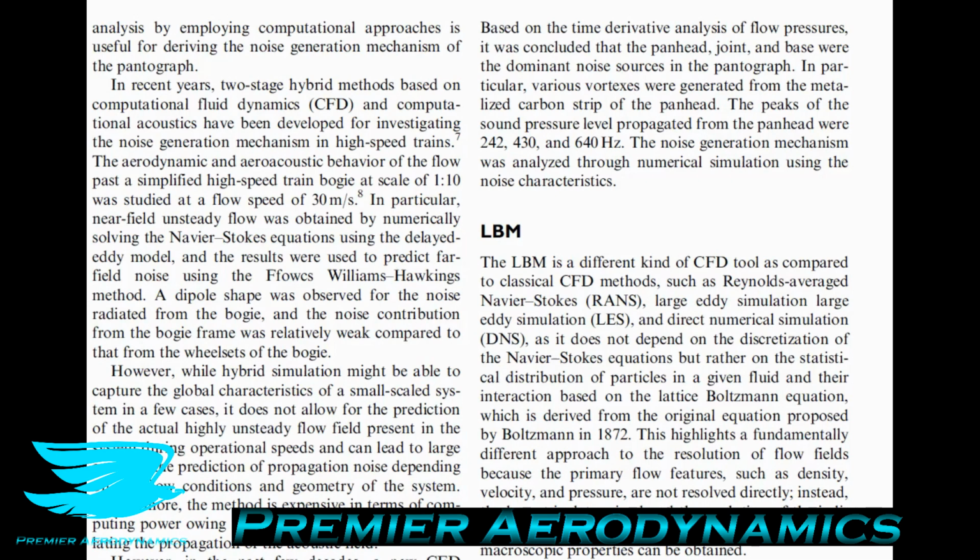Traditionally and notoriously, CFD does not pick up octopoles very well, and even quadrupoles not so well. So dipoles, URANS is okay at, but quadrupoles and octopoles it is terrible at. You then go to DES and then LES and so on if you want to get these more delicate sources of noise.